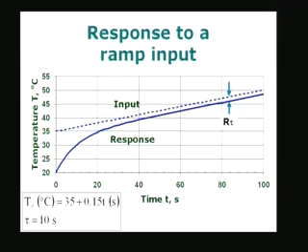So this is what is going to happen in the case of a first order system whose response we have plotted for a ramp input. When the temperature of the ambient is changing linearly with respect to time, there is always a lag, whether it starts with a lower temperature as in this case, or a higher temperature. If it were to start with a higher temperature, it will cross over somewhere. So, what is this crossover? Because the temperature of the sensor is lower than the ambient temperature initially, it will be a heating problem.